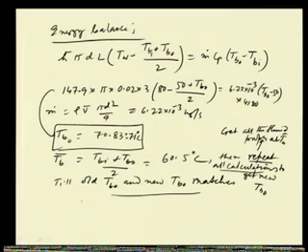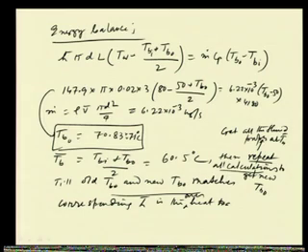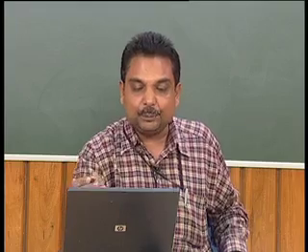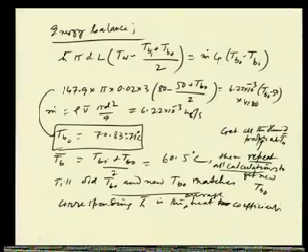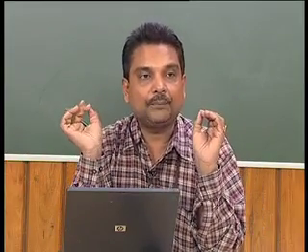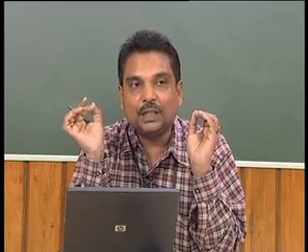Then that is called the exit temperature of the fluid, and the corresponding h bar is the average heat transfer coefficient. So, basically this is becoming repetitive, and through these repetitions we will be marginally improving the values that we are calculating. So, this is a demonstration of the problem of flow through an internal tube in laminar flow situation.